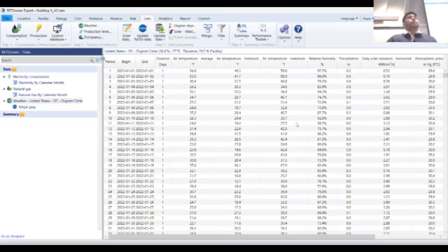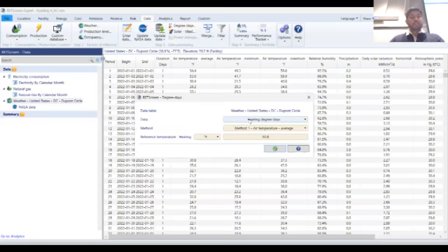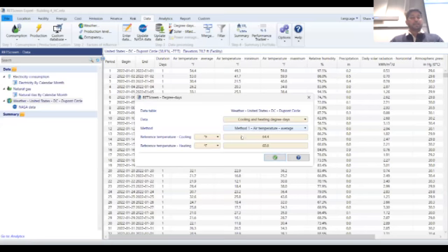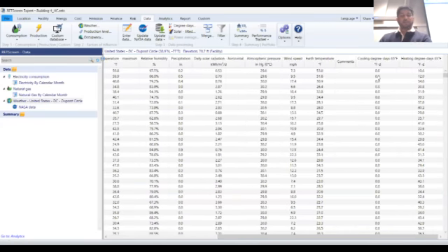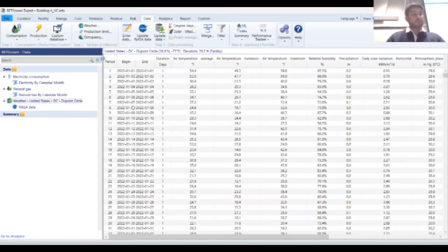But I also want to see my heating degree days and cooling degree days. I want to compare natural gas with heating degree days and electricity with cooling degree days. There's an option called degree days on the top. I click on degree days. If I only want heating degree days, I can select that. If I want both CDD and HDD, I select that. I am going to assume my reference temperature or base temperature, as some call it, as 65 for the time being, and I just run. And if I go on the rightmost columns, you'll see the CDD and HDD populated from 2022 to 2024.